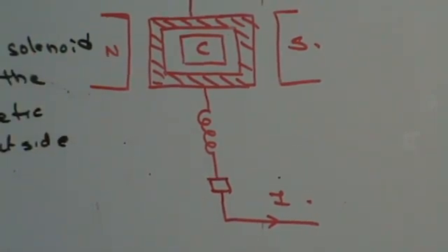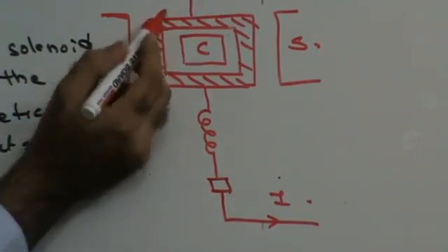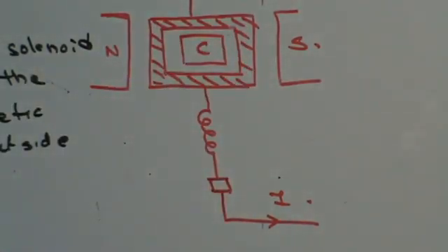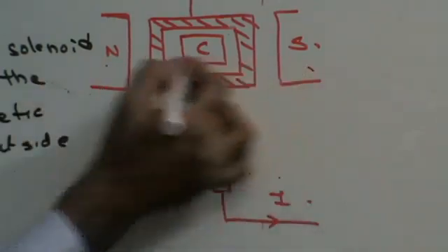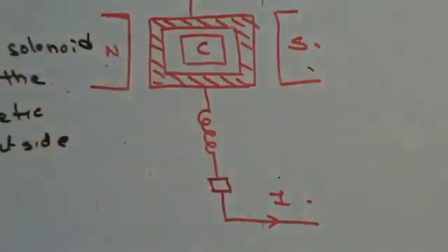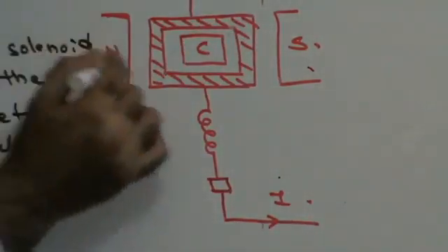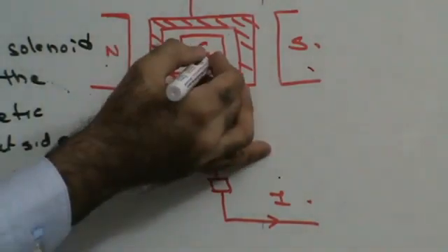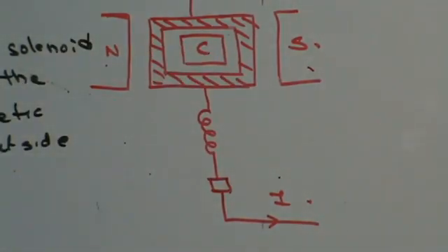It consists of a rectangular coil of thin insulated copper wire. This is your rectangular coil of thin insulated copper wire, which is suspended between two cylindrically concave pole pieces of a horseshoe magnet. These are the magnets. So this is your coil on which you have an insulated wire which is suspended between two poles of the magnet. C is the soft iron cylinder that is placed at the center of the coil, so that you have a magnetic field generated here, right?